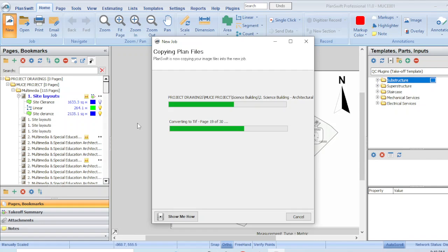Before starting measurement, I think quantity surveyors understand, before you start your measurements, you have to do technical auditing of your drawings. You have to read your drawings. You have to understand them first. You cannot just start doing measurements without reading the drawings, doing the technical auditing, knowing which drawing you are going to use for measuring a certain item.